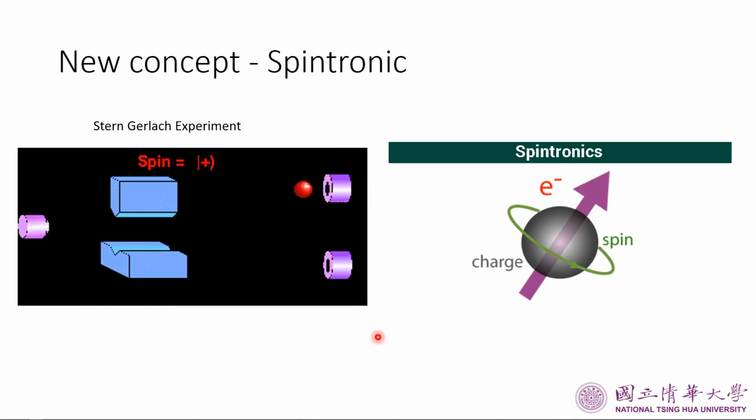Are there any applications of the spin in the electron? Of course, for example, it can operate faster compared to conventional MOSFET, in which charges accumulate in resistors or capacitors and often suffer from RC delay and non-ideal effects such as the short channel effect.